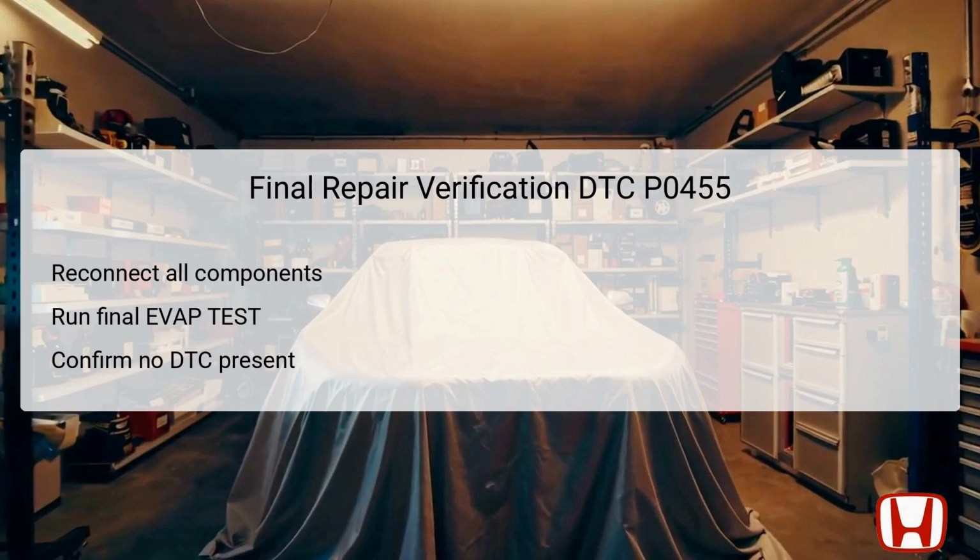After performing all troubleshooting steps, it's crucial to reconnect all components that were disconnected during the diagnostic process. Once everything is reassembled, conduct a final EVAP test using the HDS to verify that the repairs were successful. This test will confirm whether the previous DTC is still present or if it has been resolved. Checking for lingering codes helps ensure that the EVAP system is fully functioning as designed. Successful verification not only means the repair is complete, but also instills confidence that the vehicle will operate efficiently and be compliant with emission regulations.